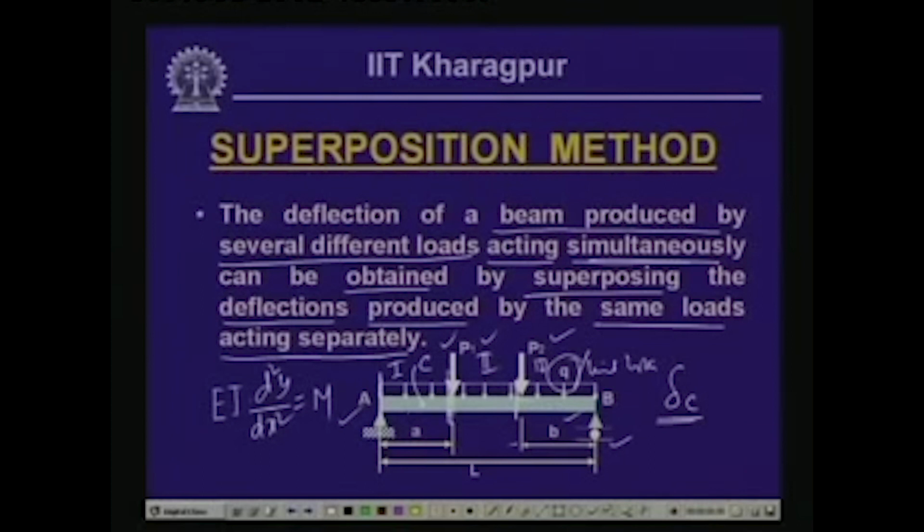At these three places we can take the free body diagram and compute the moment, and substituting in the differential equation, we can obtain the value of y with appropriate boundary conditions for the different segments. We will get y as a function of x, so at a distance x from here, we can compute the value of y.